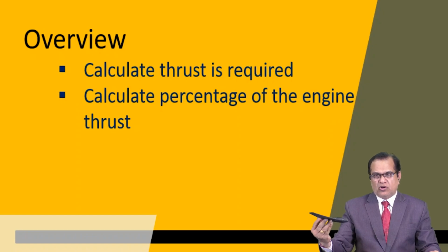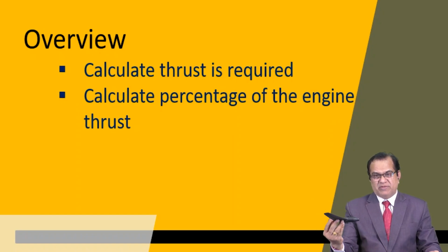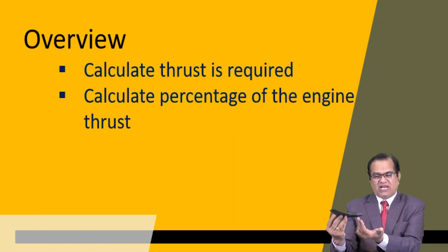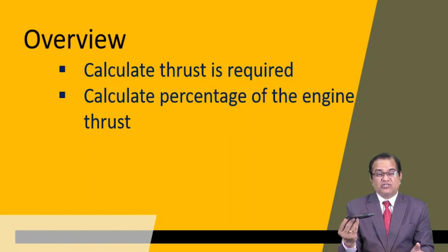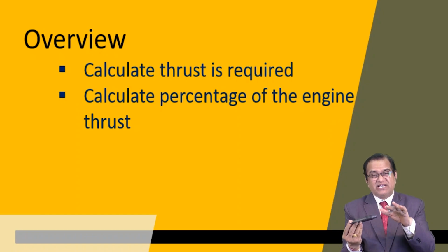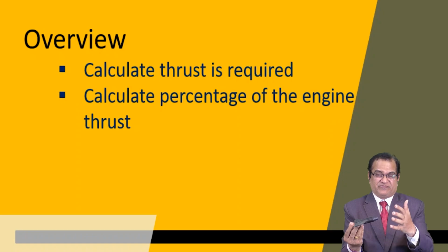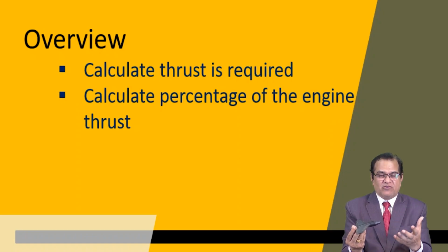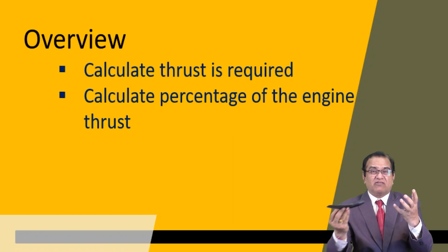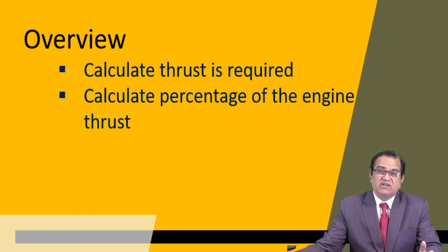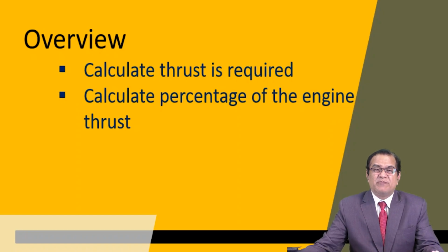Then it has to rotate, meaning the nose wheel will be up and the main wheels will be touching the ground. Then it has to transition. In transition, it is acting as a pull-up maneuver, and after reaching this, it will continue climbing. So these are the 4 stages of the takeoff of the aircraft. The same way it happens for landing also.